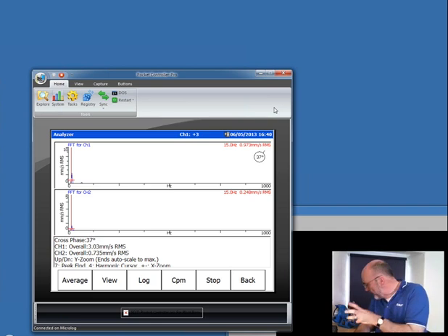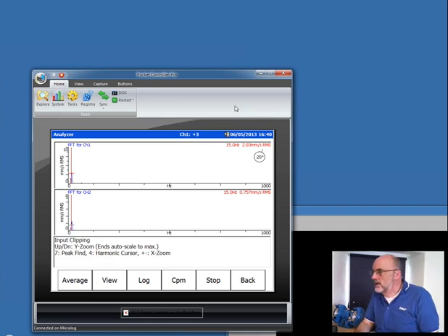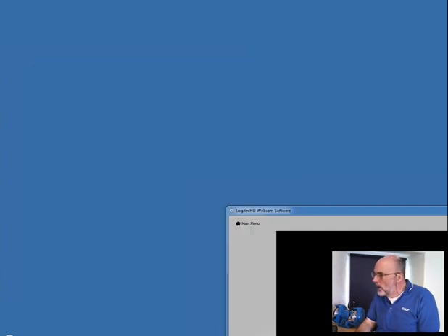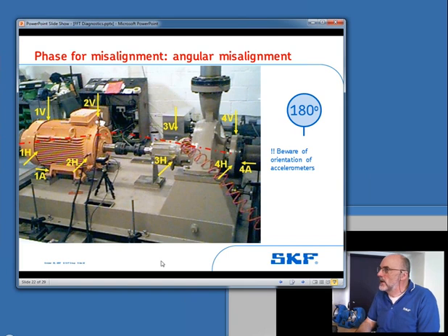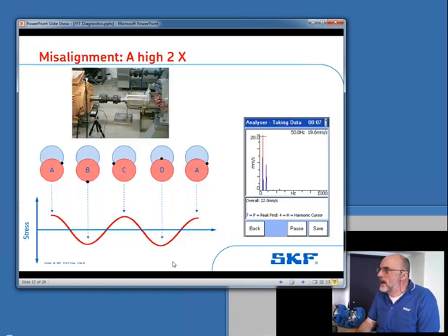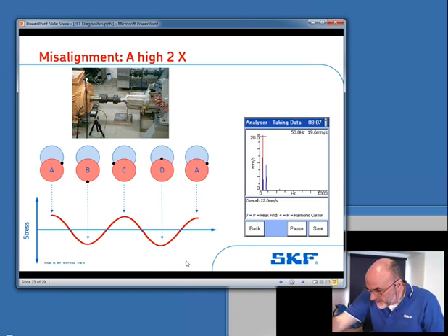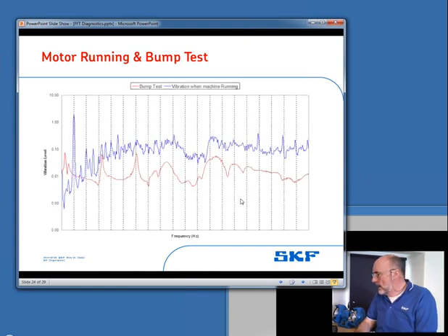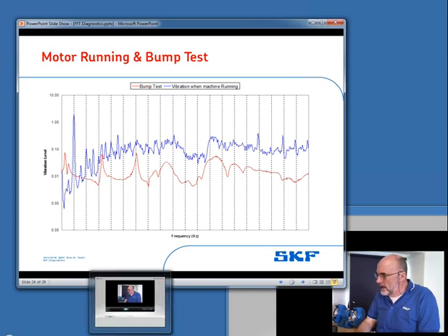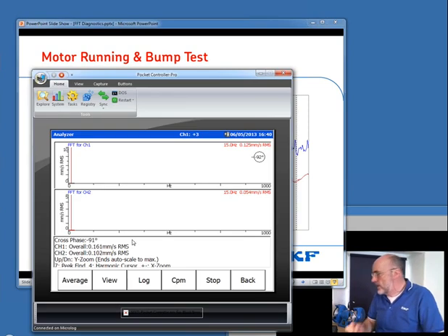Again, this is using an FFT analyzer to harvest evidence for your diagnosis. And last week we did motor current analysis, and I'm sure that would have manifested itself in the motor current spectrum as well. 2 last things to show you before the hour is up. One is a structural test, and I'll do that one live for you. So we'll do a structural type measurement.